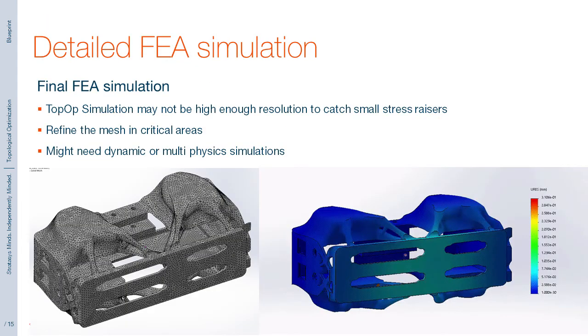Now we have a CAD reconstruction with some light human input, it's a sensible time for us to check our work with a much more detailed traditional FEA simulation. The initial top-op software we ran to optimize our geometry was a simulation, but as I explained before, quite a low resolution or fidelity simulation. By using a much refined mesh, we can ensure there aren't any small stress raisers or areas prone to failure that the previous top-op simulation might have missed, and especially given the fact the design we are now working with was altered by us in the previous stage.